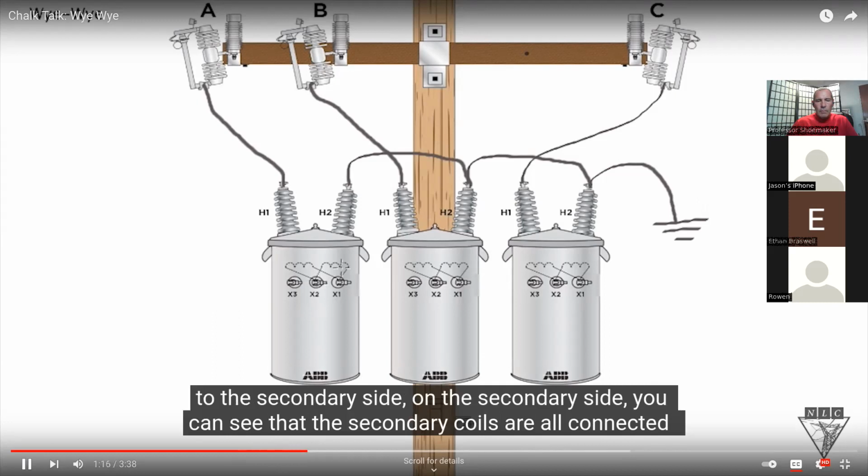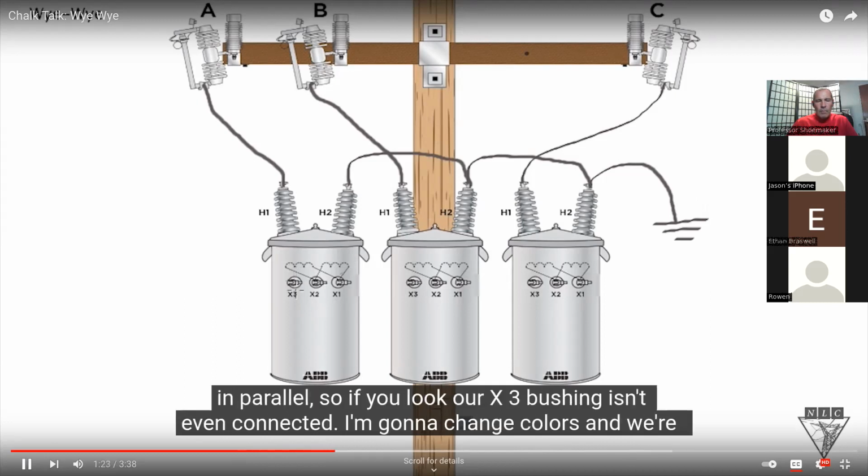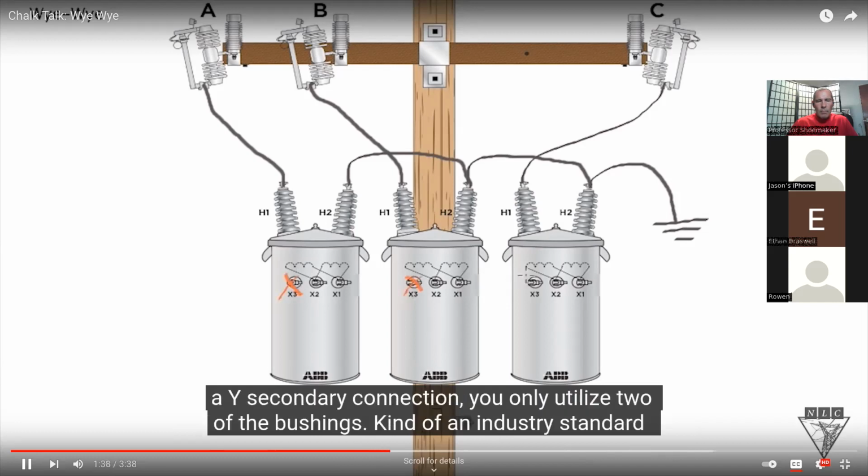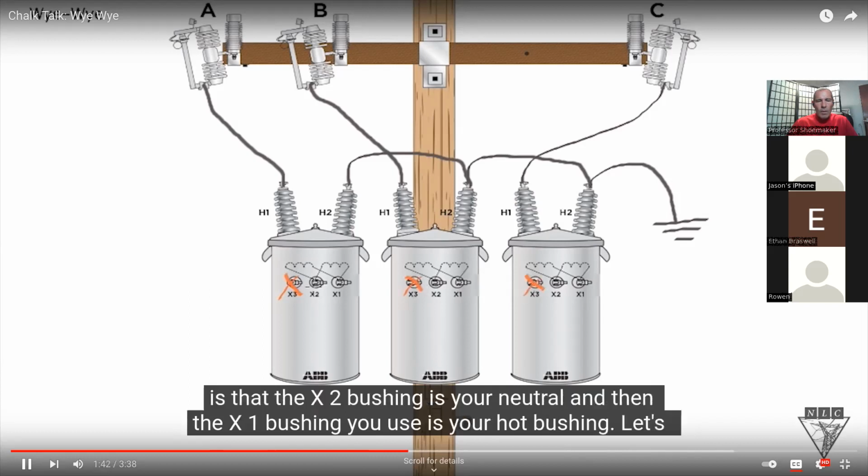On the secondary side, you can see that the secondary coils are all connected in parallel. So if you look, our X3 bushing isn't even connected. I'm going to change colors, and we're going to put an X through the X3 bushing since we're not going to be using it. This is for a Y secondary connection. You only utilize 2 of the bushings. Kind of an industry standard is the X2 bushing is your neutral, and the X1 bushing is your hot bushing.